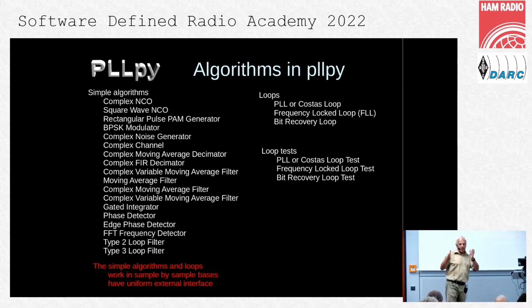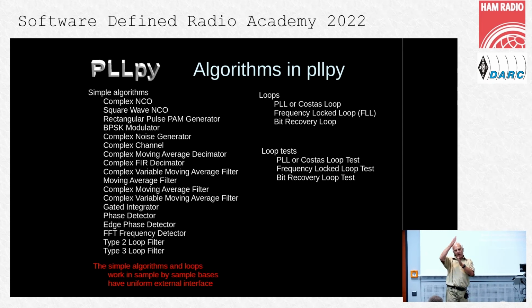It works in such a way that it gets all the samples, and there is an output flag which signals that there is a new valid output sample. And between the 2 flags, it will output the last valid sample.